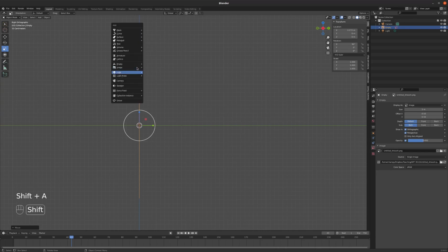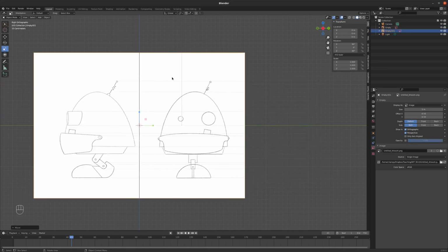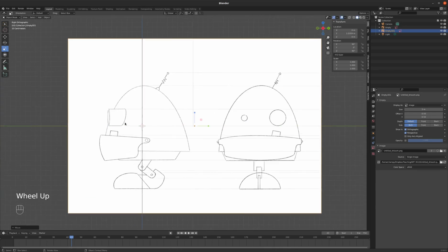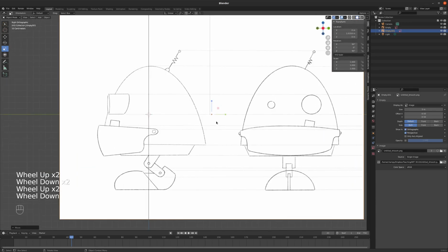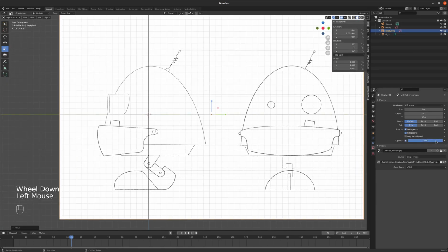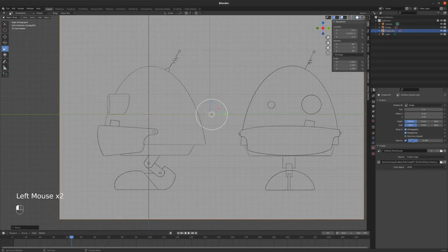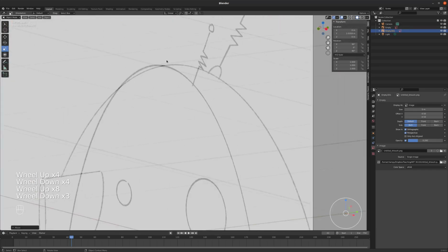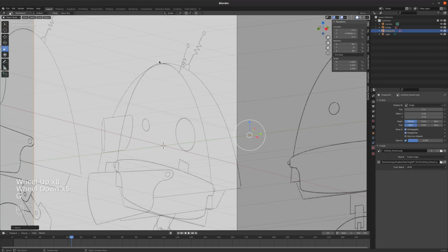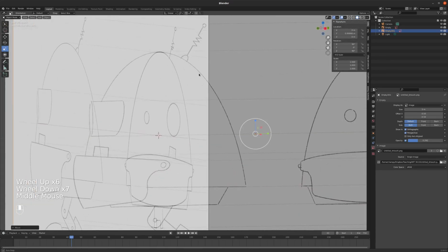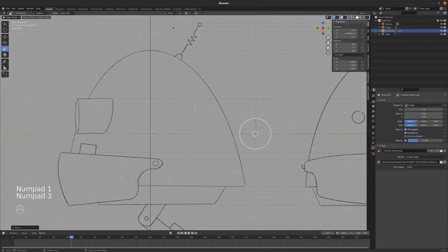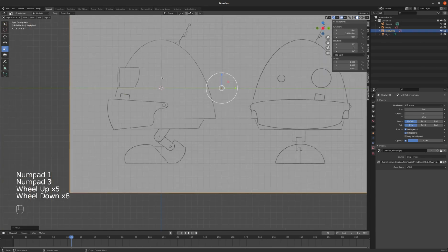I can actually just do the same thing again. I can do an image reference and bring in my artwork here, and then align the right side view with an axis. The character is not symmetrical in this axis, so perfect alignment is not critical. But vertically I want these aligned the same way so that you can turn them and see that, yeah, okay, they intersect. And that's probably a good idea to have the crown of the head intersecting there. So that'll be how I align that horizontally. I want it to be right at the top of this egg shape here.